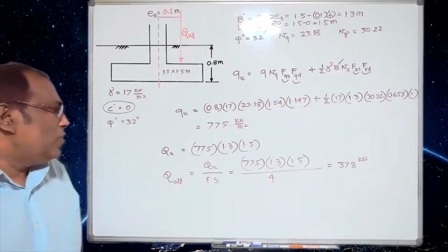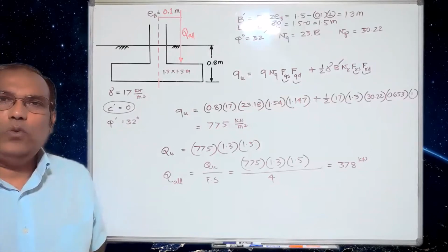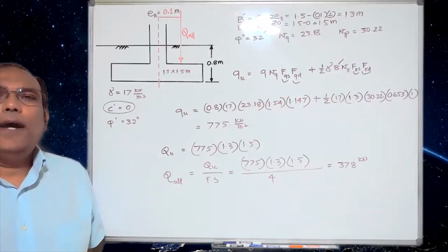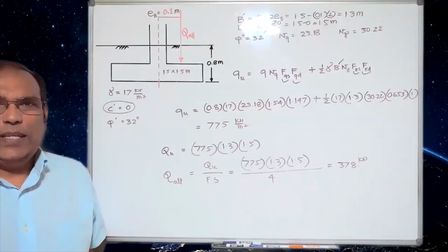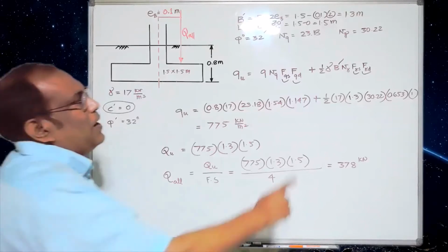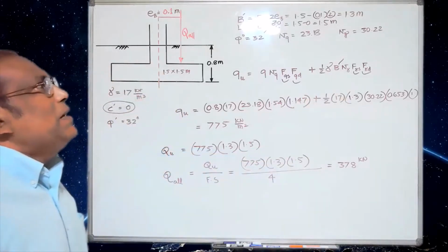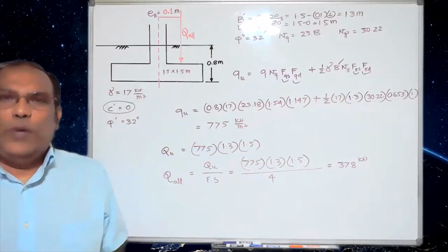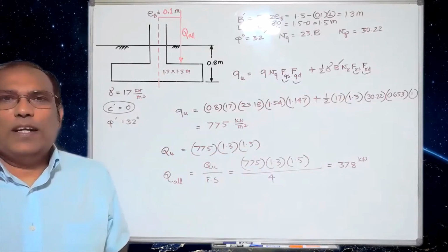When you find the depth factor, you have to use the original length and width. And the last part here, this one is your B prime, meaning your effective width. Now let's move forward and see the next problem.